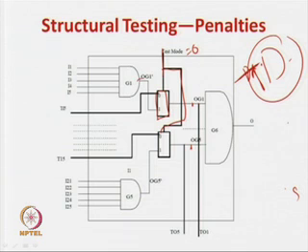Let us say that you apply 1 over here first, in the test mode. So in the test mode if you apply 1, then what happens? The output of the gate, through this 2:1 multiplexer, gets directly connected to this AND gate and the circuit functions normally. So in this case also, if it is 1, this output is connected here and it feeds this AND gate and the circuit is doing a normal operation.